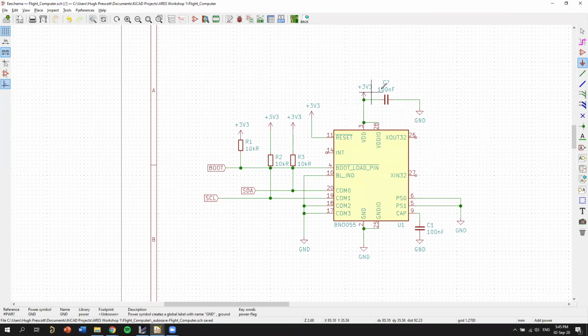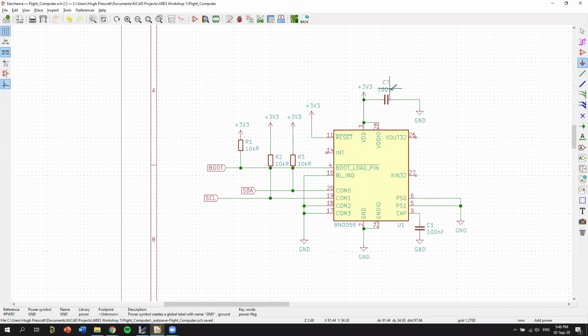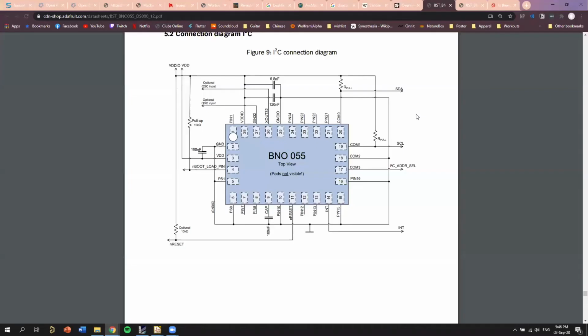It's probably not that useful, but that's just to smooth out our IO lines. Honestly, what I'd regularly do is add another capacitor on the input voltage here, like a 1 microfarad, and that smooths out the slower noises, not the high frequency noise. But we don't have to worry about that right now.